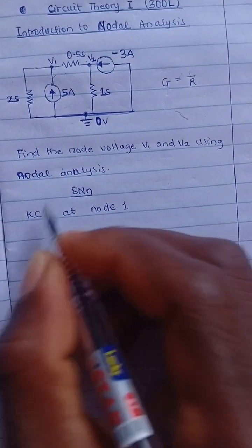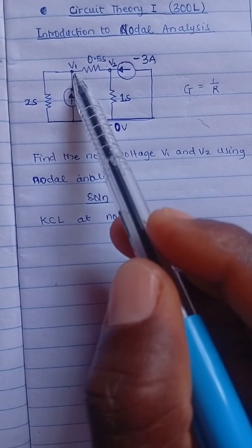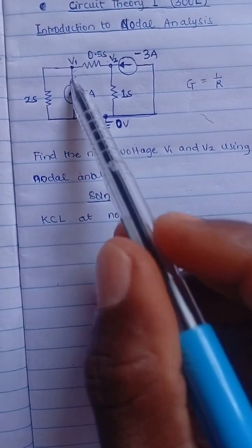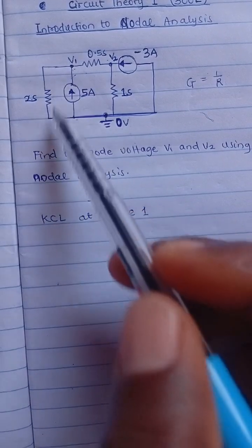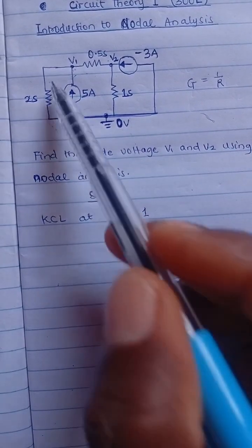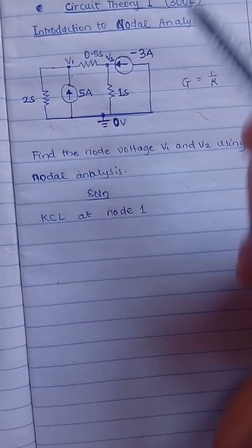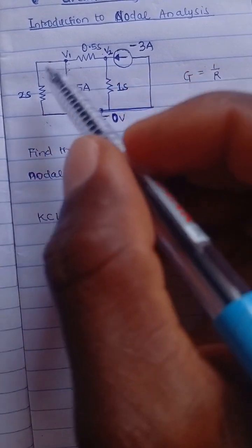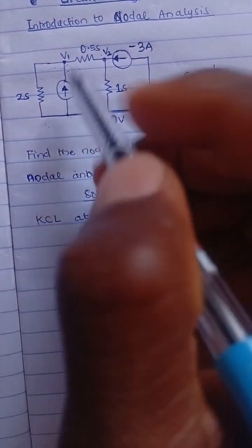At node 1, you apply KCL. You talk of current entering and current leaving. Now, if there is a voltage drop across the resistance, you will know that there will be a current passing through it. This is what I want you to pay attention to. If, for instance, I'm concerned about the current flowing out of this node, then here has to be the positive terminal, here has to be the negative terminal if current has to flow this way, isn't it? Similarly, if current has to flow from node V1 to node V2, then I will have to consider here to be, for now, the positive and here to be the negative terminal.